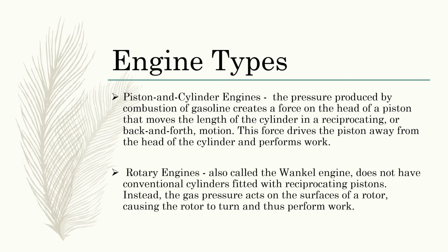First, let's define what a piston and cylinder engine is. The pressure produced by the combustion of gasoline creates a force on the head of the piston that moves the length of the cylinder in a reciprocating or back and forth motion. This force drives the piston away from the head of the cylinder and performs work.